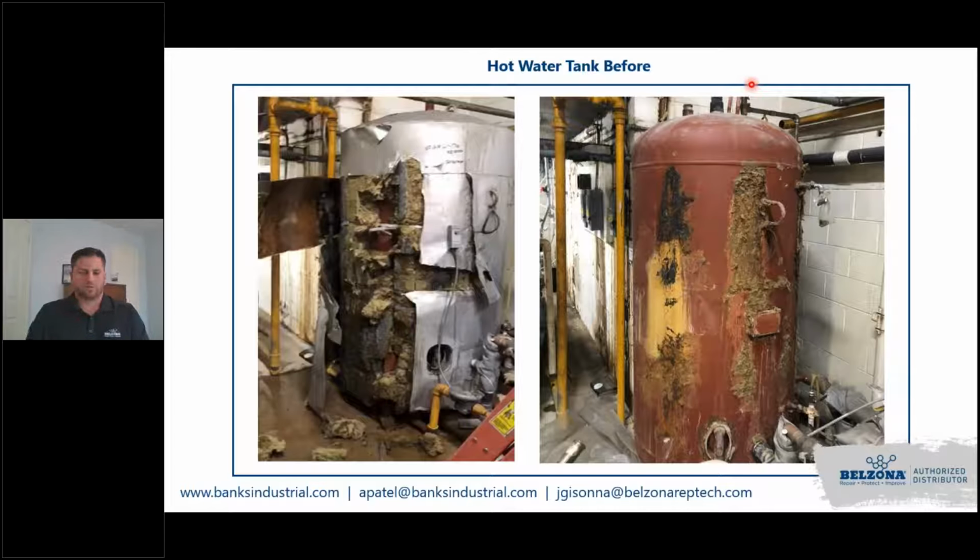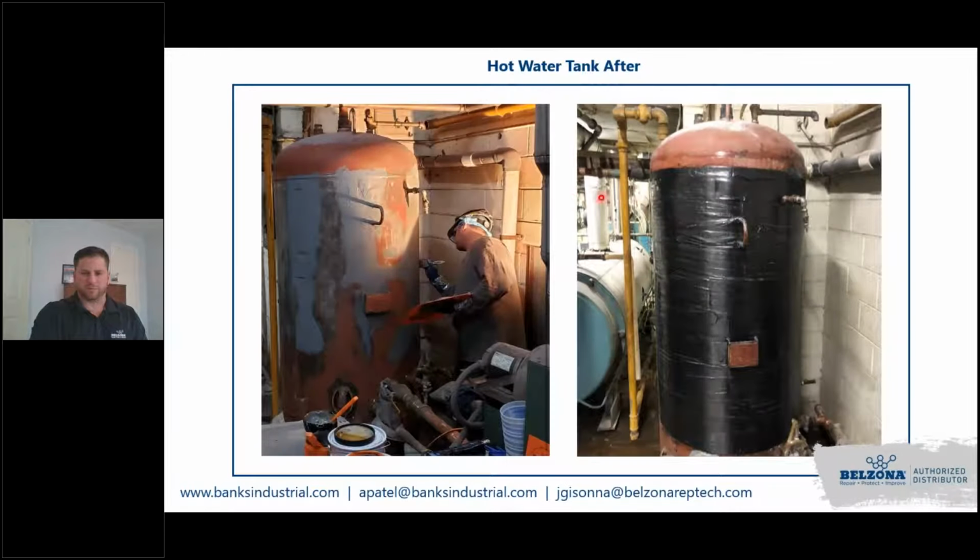So what we had to do was be careful with removing the insulation. AJ already showed you the video. We uncovered 10 to 12 different leak spots on the external, some that were located closer to the welds. And if you could follow my laser pointer right here, you'll see some of them. And once we removed all of the scale buildup and located all of the through holes with inspection, we were able to isolate these areas with another Belzona 1000 series stopgap and use an epoxy composite paste.